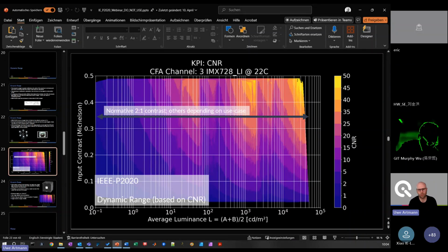And there's another trend in the industry where there is some color processing, also for machine vision, which tries to level all cameras. I personally think that is a better approach because it gives you more flexibility: you define for yourself some common ground of color that doesn't have to be human vision color. It doesn't have to be sRGB or XYZ color space, but you define your own color space, bring all colors into this space, and then process further.